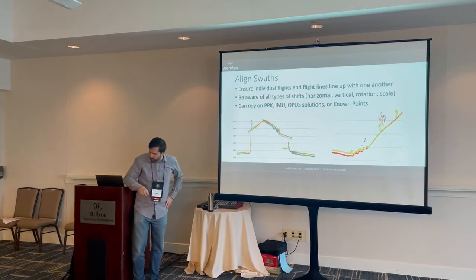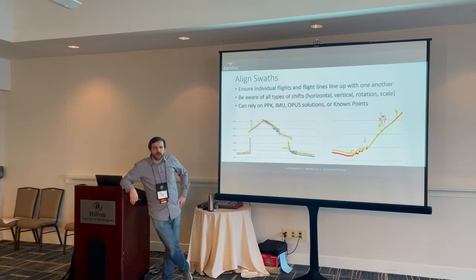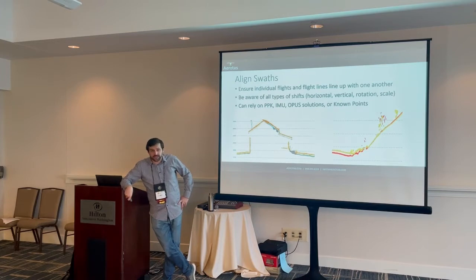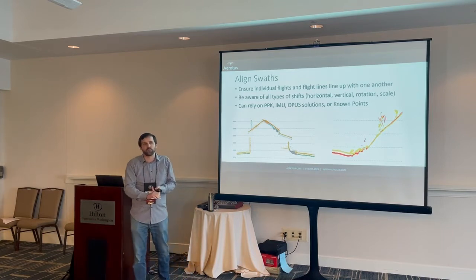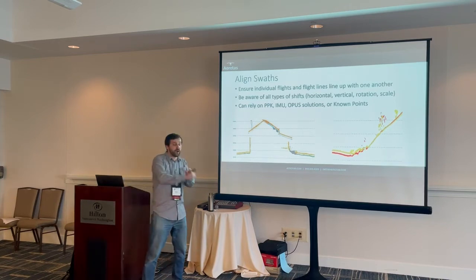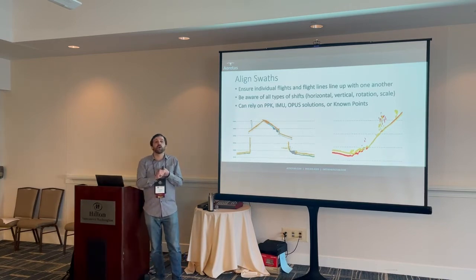That's a tricky one that honestly goes a little bit beyond the scope of this talk in terms of the detail of exactly how you can run the GPS processing workflows, because that's a very complex set of different options, of which, like a lot of these things, there is no exact right solution. As I said before in some of my other talks, our preference is always real-time kinematic GPS data with a local base station, and then we can run any corrections that we want in post, but there are other ways to do it.